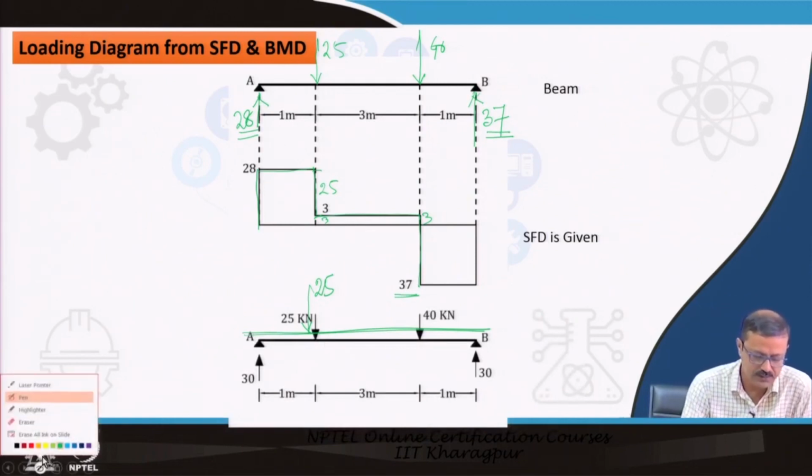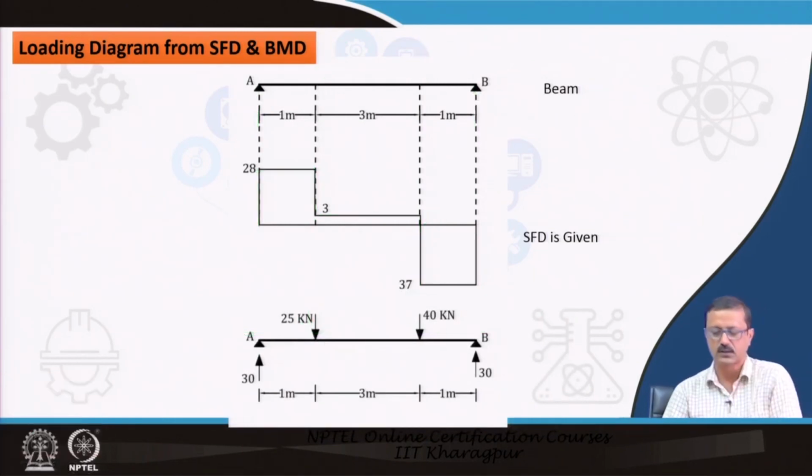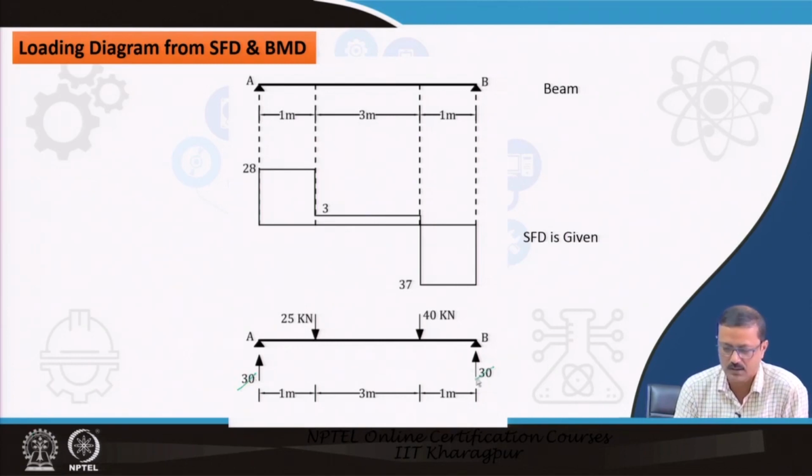From the SFD you can easily find out, step by step, first try to find out what the reaction loads are. But here I have again made a small mistake. These reactions are not 30-30, these reactions are of 28 and 37.